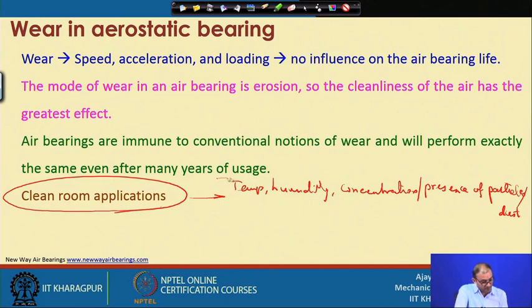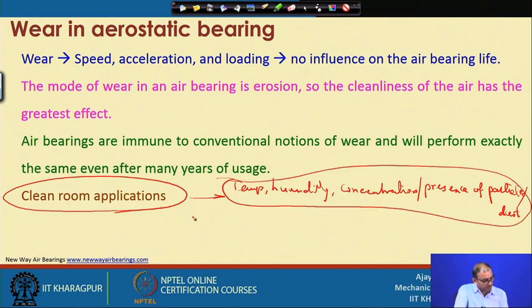If you maintain one particular limit, then there are different clean room classes: clean room 10,000, clean room 1,000, clean room 10, clean room 1. The higher the rating, the stricter the maintenance. For example, you maintain the number of 0.5 micron particles present in a volume, such as a 1 meter by 1 meter area.